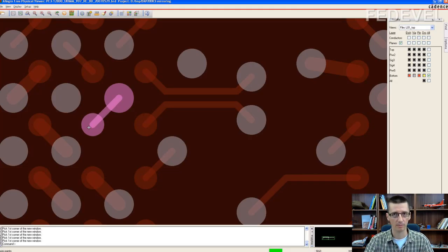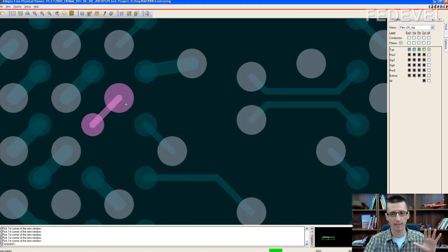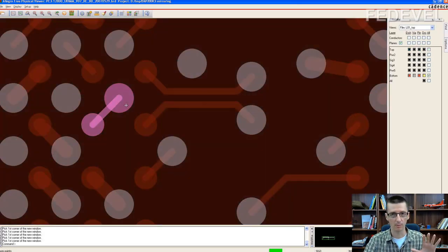How is it possible? It is possible because you can do the pin swapping. So basically, if you have this kind of situation, what you need to do is you route the top memory chip, and then you assign the net to this via, which is here. And then when you will be connecting the bottom memory chip, you already know what is the signal here.